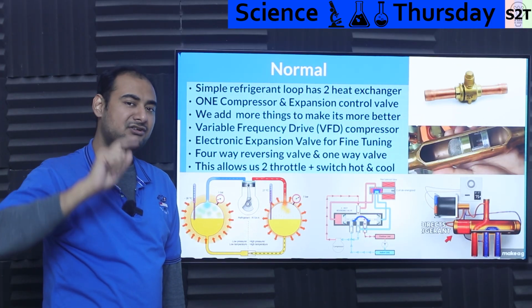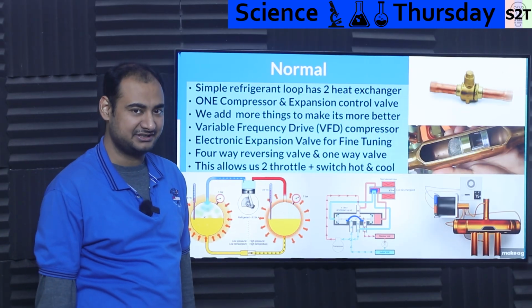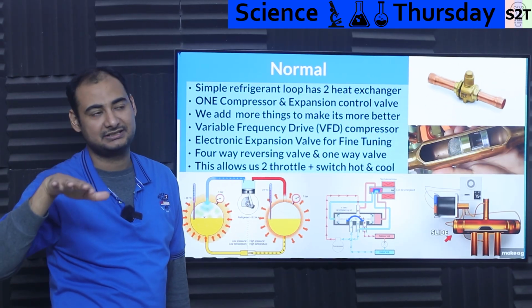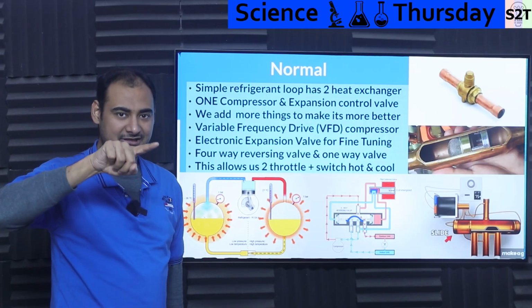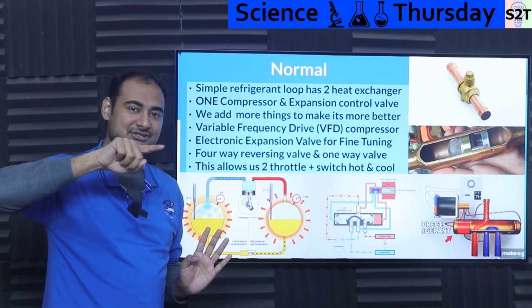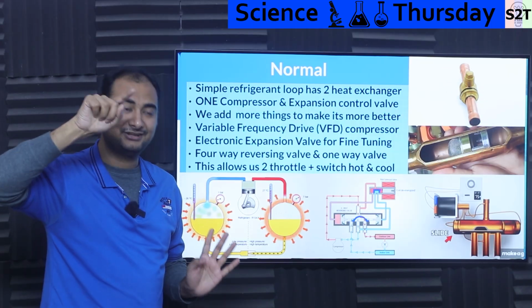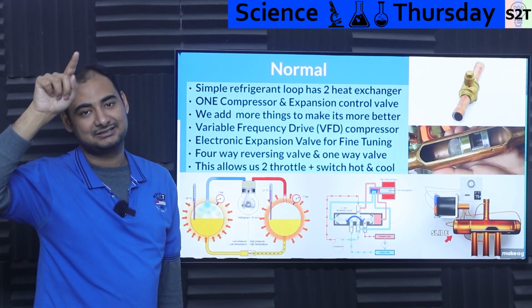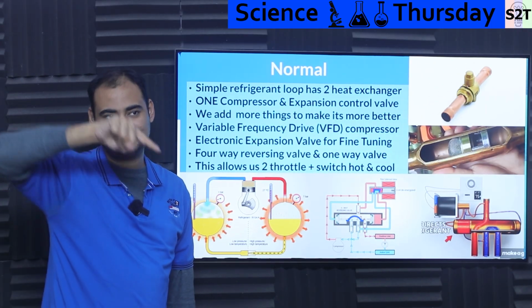Here's the deal. It will not stop there. The compressor will not turn off at 25. The compressor will wait for it to go to, let's say, 23. It will go below. Then it will wait for the temperature to rise above 25. Once it rises above 25, it will keep cooling it down until it goes below again. So there is an oscillation there.